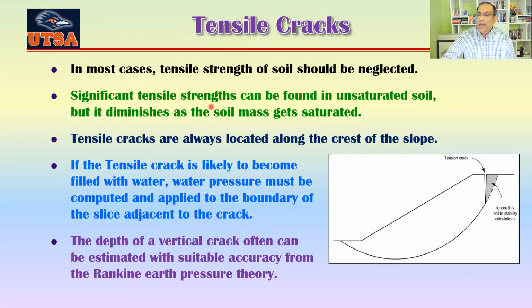And you can see here that these are the cracks that form at the top of the slope, very common there. They can become filled, sometimes with water. Okay, so I have to show the water pressure on this part, because we are going to take this part off from our calculation, because the failure will not occur along that line since there is already a crack here.